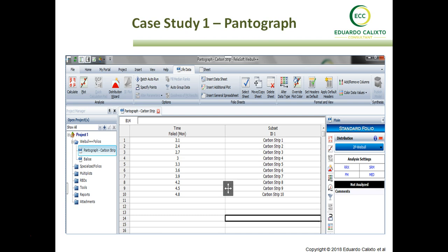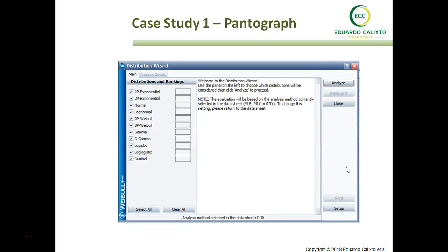But before that, of course, I need to select the model here. I select the rank regression model in X to carry out the assessment of which PDF best fits such data, as well as the ranking for the reliability plots and the Weibull PDF. Since I defined the regression method to define my PDF, all the calculation presented in the previous module will not be necessary. Here we can already see all the possible PDFs that we have in this software, the Weibull software from ReliaSoft.